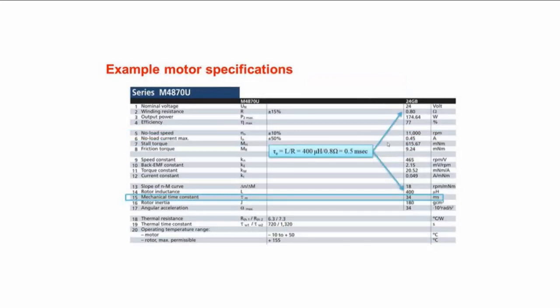Okay. Now after class, please download a motor company datasheet. For example, I say to you Maxon Motor. You can download the Maxon Motor datasheet. It is very detailed. You will see lots of these parameters. You can search on the internet for the nominal voltage, the no load speed, the stall torque, the friction torque, etc. These parameters are very critical.